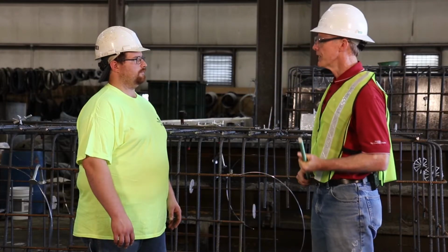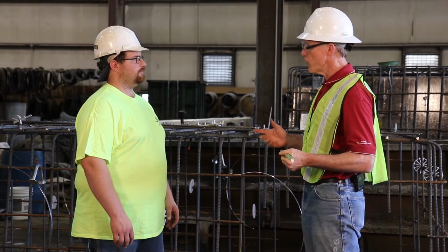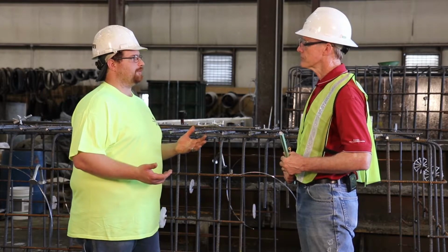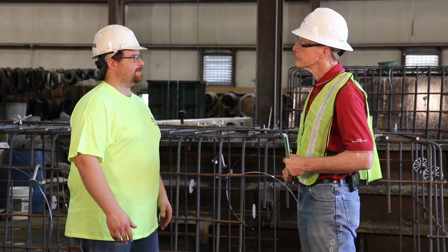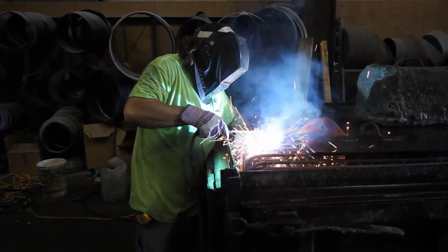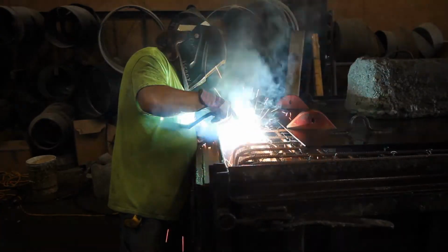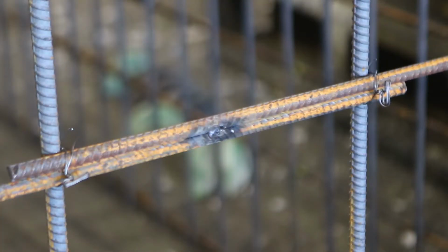So Michael, the next item that we have is the overlap and tack weld method. Can you walk us through that process? Yeah, so the overlap with the welding is actually quite similar to the tie method. The only difference is we're tack welding it just to keep it in place. The load transfer between the steel bars is still accomplished by having the proper minimum overlap, and the tack weld simply holds the sections in place. Even though this is not a structural weld, you do not want the weld to burn up the connecting steel or wire and reduce the reinforcing area. Make sure you're using proper technique when making a tack weld.